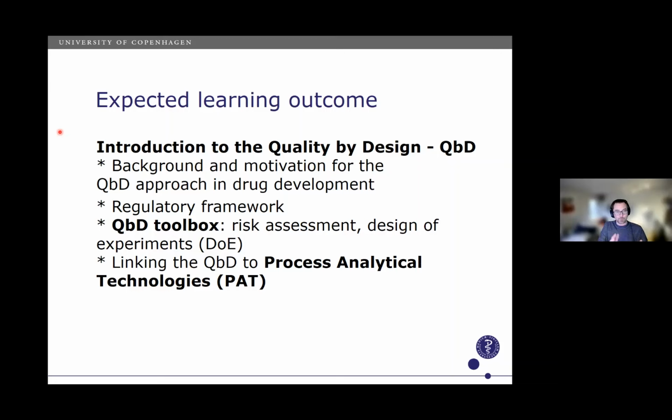It is also important that you link these activities towards process analytical technologies, process measurements. PAT is a set of different analytical tools that can be implemented into the production environment. By this means, we can increase the level of understanding of what is happening during the processing, and then keep the product under production under control. The key goal of quality by design is to build up a control strategy that helps you keep the production and product within the desired specification.